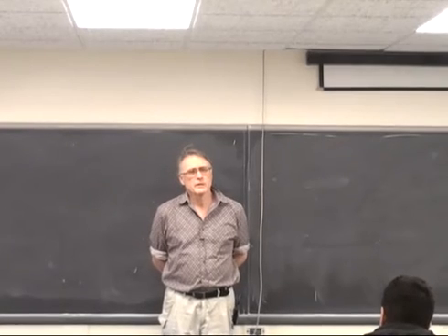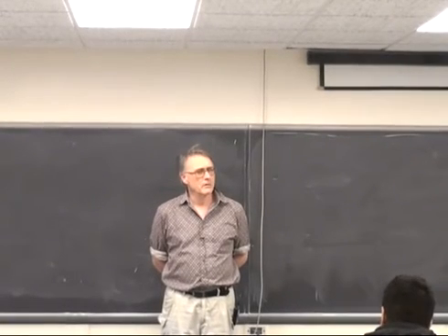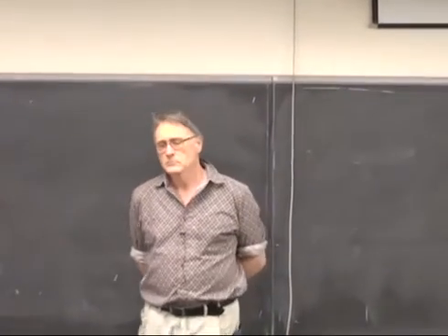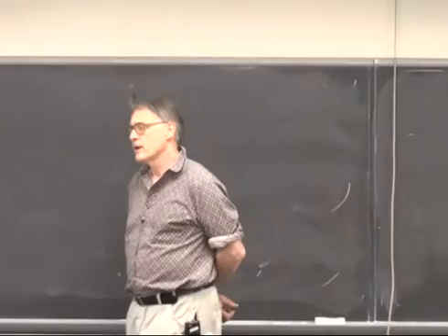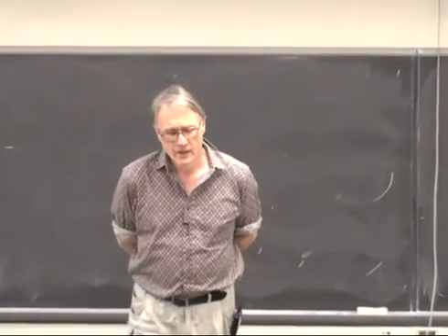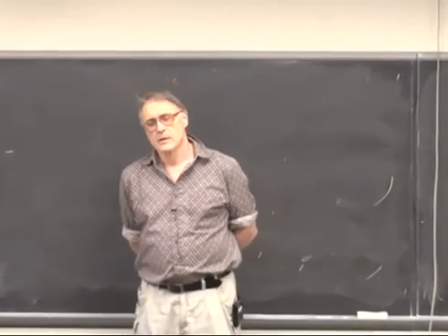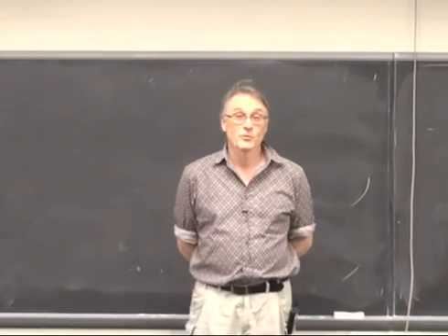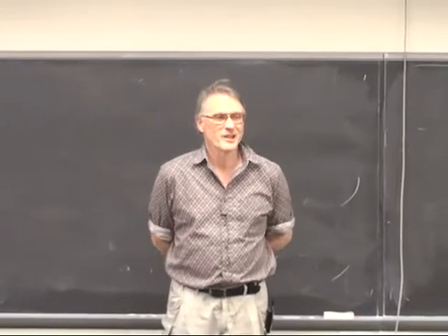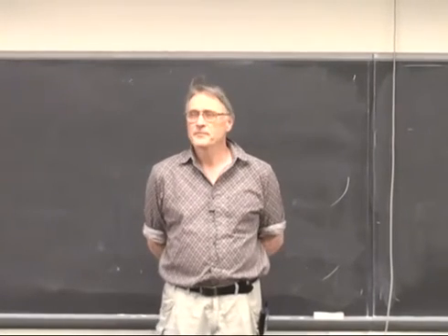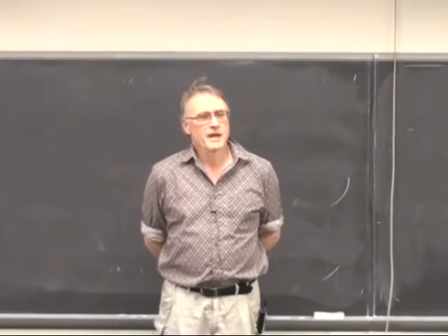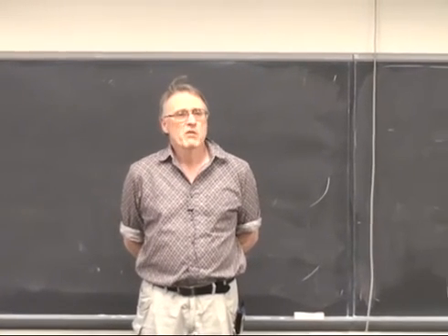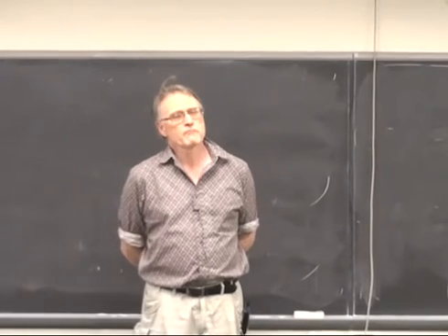Everybody get a recording? Yeah, ECG recording. Everybody saw something? And that came out better than I was hoping for, and still a little bit nerve-wracking, since as of last Tuesday nobody had recordings, and by Thursday almost everybody had recordings. So that was impressive. I guess the main trick was to jack the gain up to about 4,000 or 5,000, because the size of the signals was rather small. That's nice.